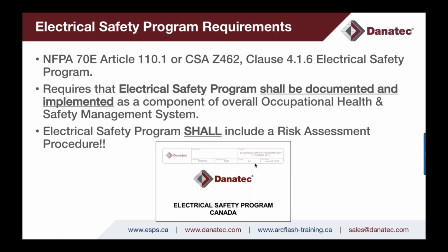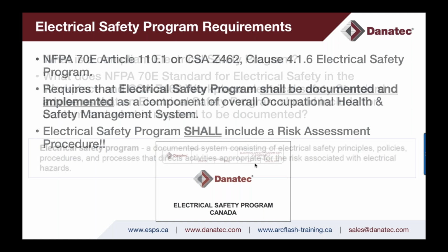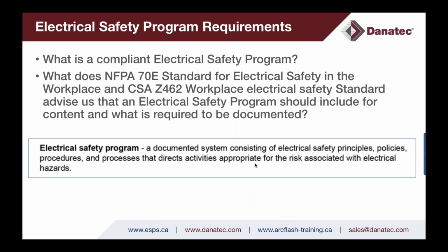Then in turn, the risk assessment procedure shall be documented for, again, energized electrical work tasks. So I often get asked, what's a compliant electrical safety program? What do 70E and Z462, in this case, tell us that an electrical safety program should include for content? The content in 70E and Z462 as far as electrical safety program requirements isn't 100% complete, but it's pretty